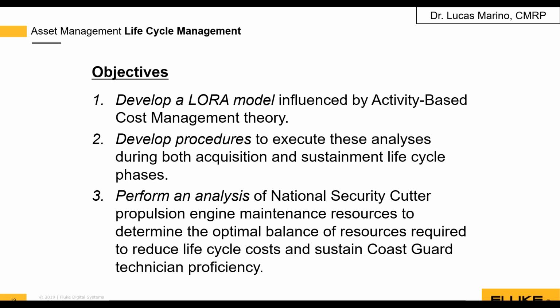right? And I wanted it to be informed by activity-based cost management. And I think this is important for maintainers because maintainers don't look at a piece of equipment and say, what does it cost to perform maintenance and surround that part with costs? What they do is they look at how much does it cost me and how much time is required and what resources are needed to perform this task. And an activity-based cost management approach gives us the ability to focus on the task and not just a part.